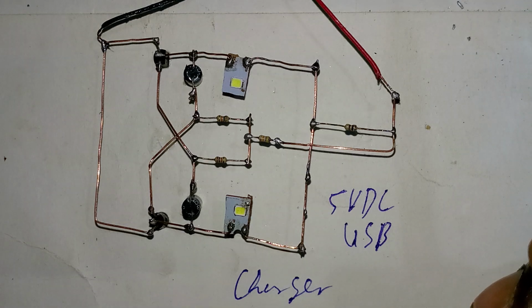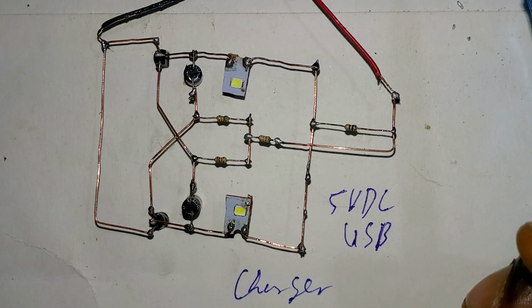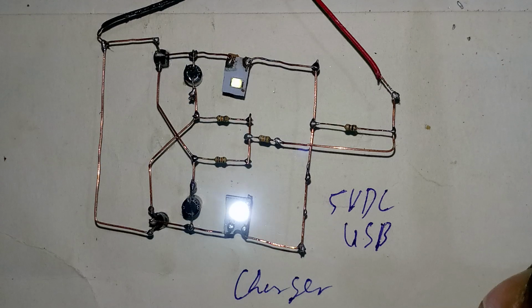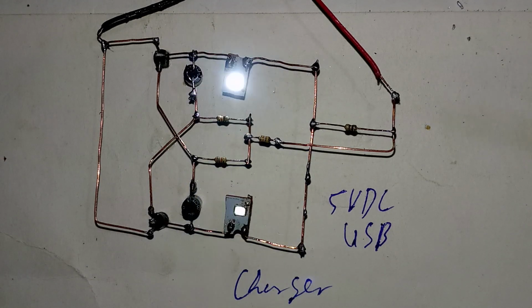The multivibrator circuit has many uses, but this is just the beginning. As we go along, we will be using this circuit to work out various projects in the workshop. Now look at the actions of the multivibrator circuit. So this is exactly how a multivibrator circuit works. As one capacitor is discharging, the other is charging. It is happening alternately, on and off.